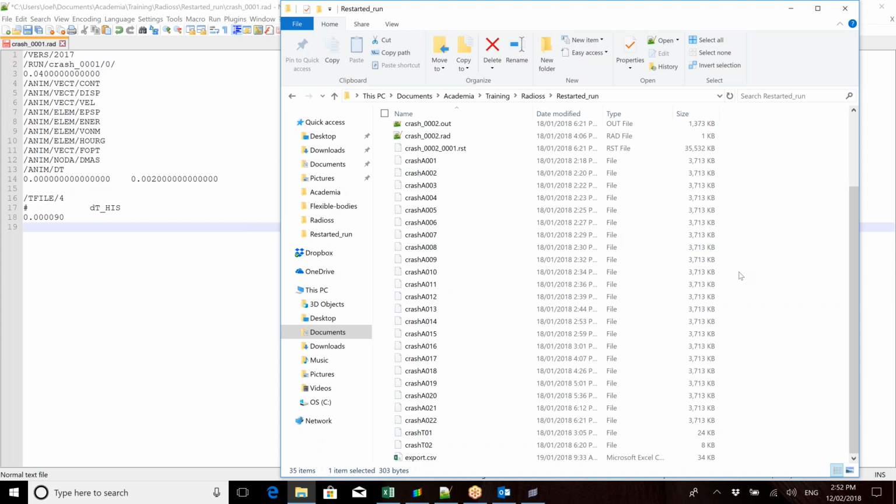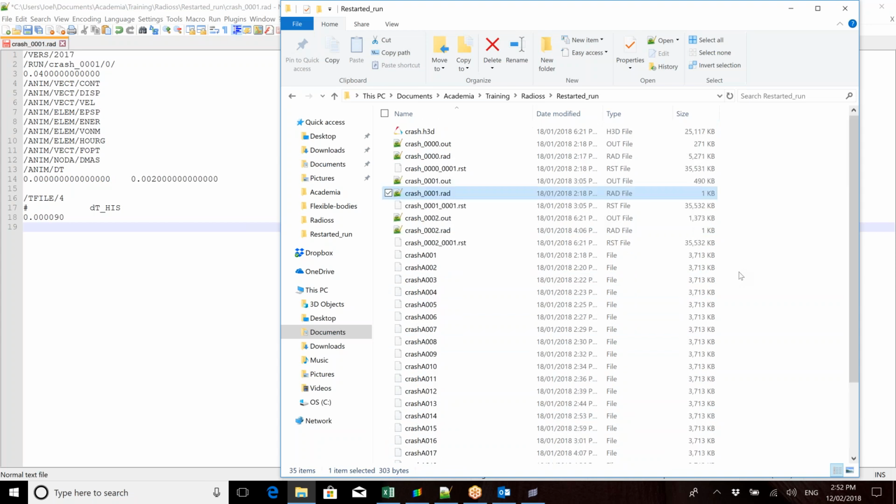And also with this, you can do a restart. One way to do a restart, and this is a big recommendation because nonlinear runs can sometimes take a lot of time, is you'd get it set up during the day, start it running just so you know it runs, and then you could stop it. This way you can continue on with all your other work without heating it, and then you can run it overnight when you're not using your computer.